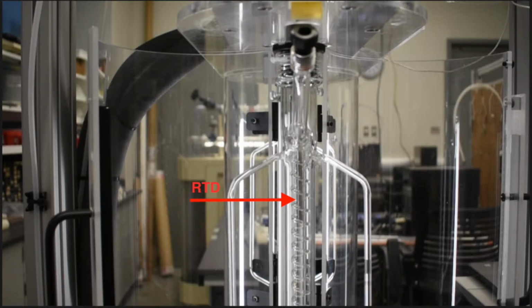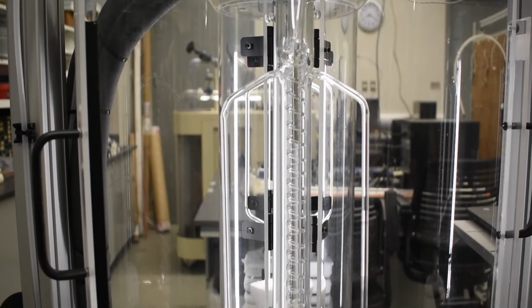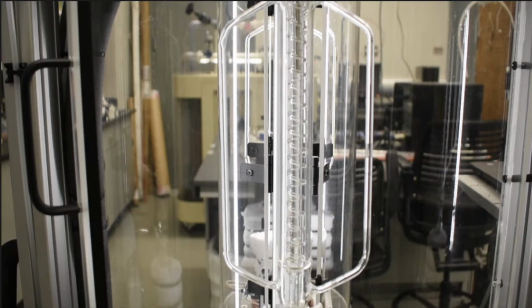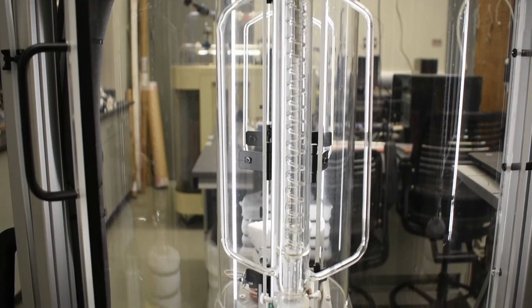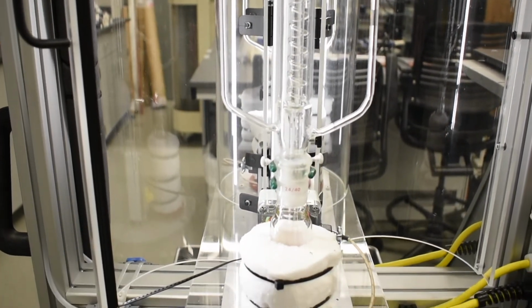That device will collect the temperature of the vapor-liquid system in LabVIEW. Once operation begins, the rising vapor phase will move up the Cottrell pumps. The vapor phase contains small drops of liquid creating a VLE mixture. Separation occurs when the mixture hits the thermal well, where gravity drives the liquid phase down to the boiler and the vapor phase will continue to rise further to the condenser.